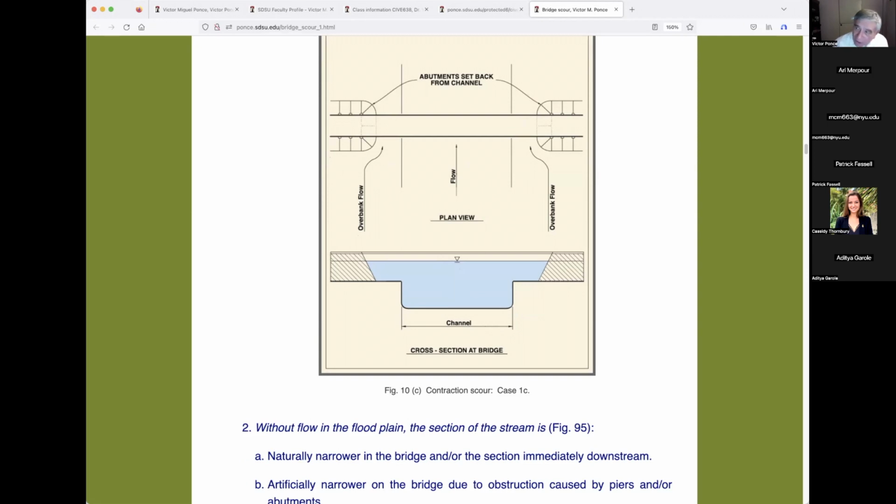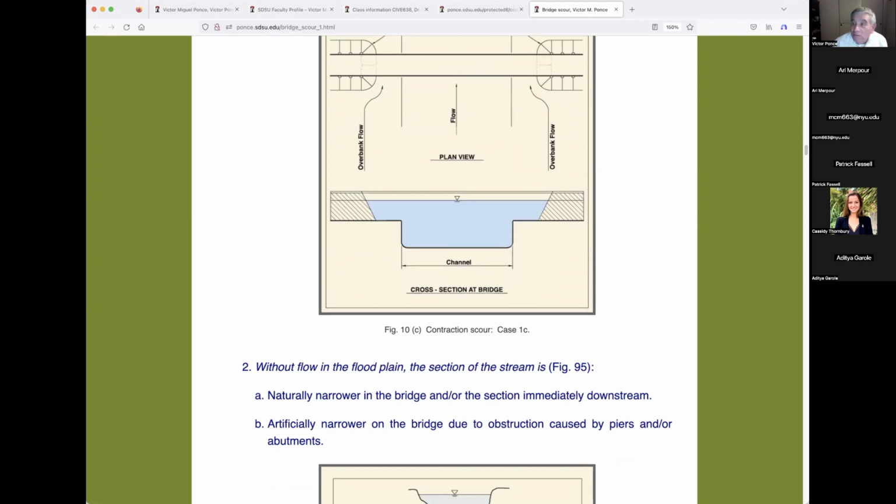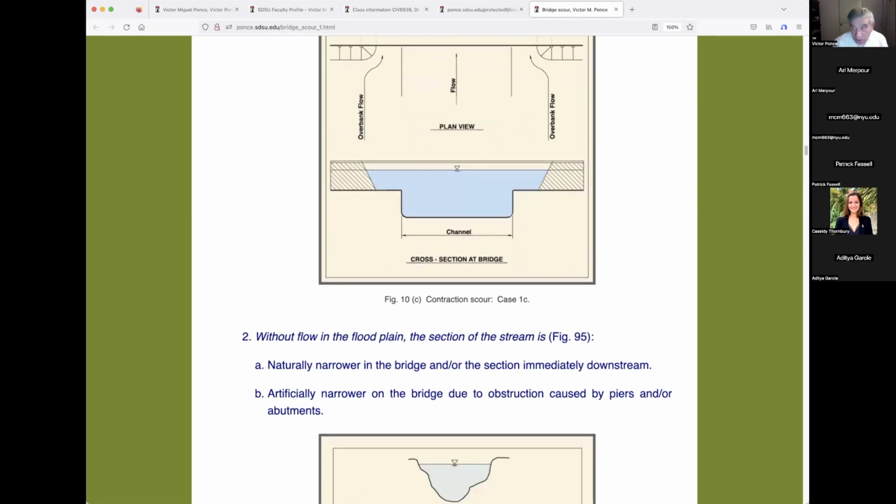If you were doing this for forecasting, steady would not suffice, because you have to go second by second or from time to time examining what's actually happening. But a design condition is just a bird's eye view of what's actually going to happen. So it's probably sufficient to use steady flow for a design condition. Because as you know, HEC-RAS has both steady and unsteady. So you're given the choice, and you as a designer have to choose which one to use.